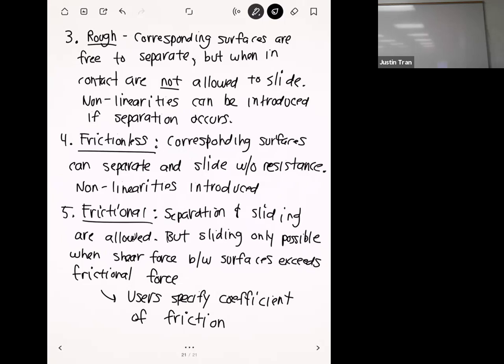So I'm keeping a coarse mesh, but where the concentrations are high, I would like to refine it. That's perfect. Yeah, because I'm doing the optimization of the disk. On the disk itself, there are high stress concentrations on the edges. So I've refined that edge, and the center of the disk is all coarse. Perfect. Sounds good. Okay, so 200,000 elements are fine, or